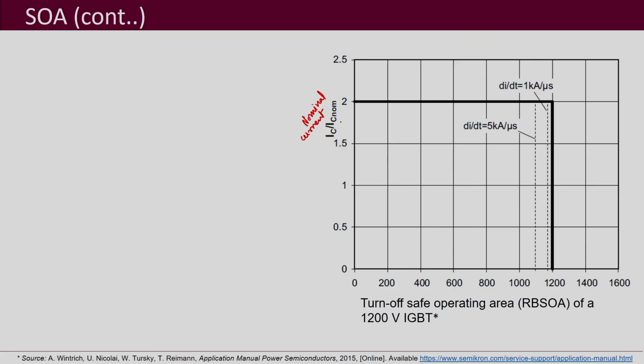So nominal rating is basically whatever each chip is capable of carrying as current, multiplied by the number of chips. Okay. So usually the ratings are close to your IC, the continuous DC current rating.